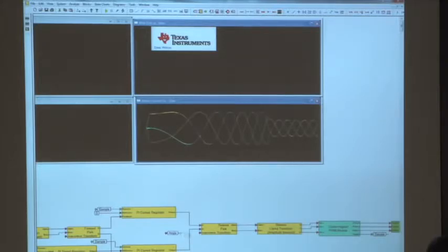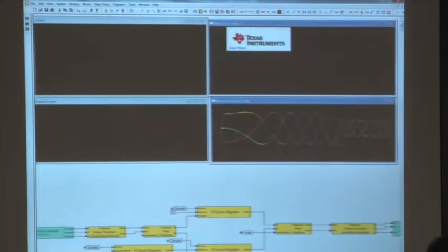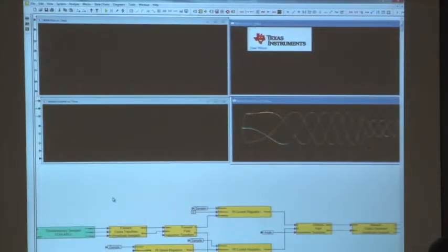I'm going to run the angle into the angle input on the reverse Park transform, and then one more Control-V for another instantiation of it, which goes into the angle input on the forward Park transform. All right, now we're getting close. One more thing that needs to be done. And that is the output shaft speed in terms of RPM.